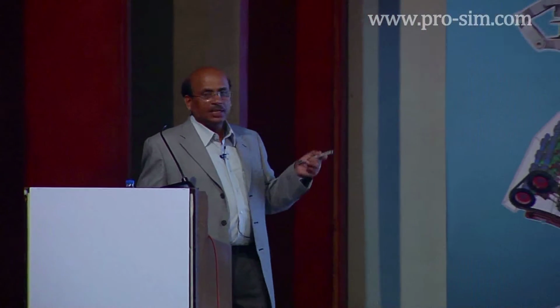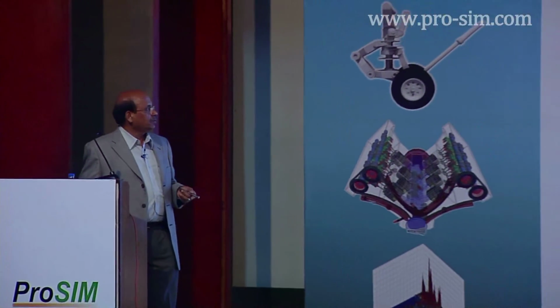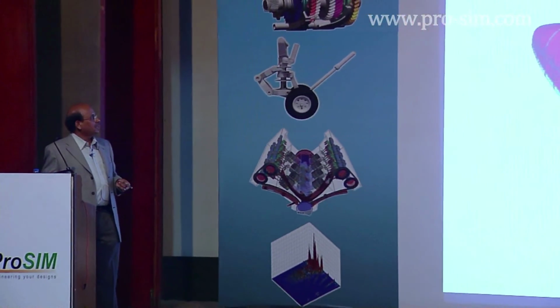Okay, let us quickly go through the RLV design details. These are the design details which were obtained in 2006, based upon which we did the analysis. I'll try to go quickly since I have already briefed. This is the actual re-entry vehicle, and this is the booster fin. The booster fin we modeled using a stick model because we didn't have complete 3D details. The RLV vehicle we modeled using the regular 3D models. This is a finite element model of the RLV.